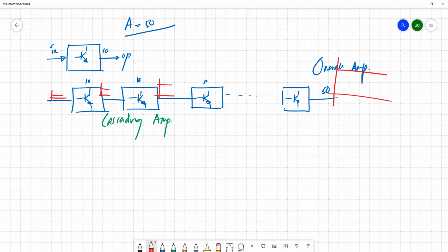So what we can do is introduce coupling capacitors here. Then whatever error is introduced by this input is never fed to the first stage, and if there is a DC offset incurred by the first stage, we can block it through this capacitor, so it never harms the biasing point of the second stage.